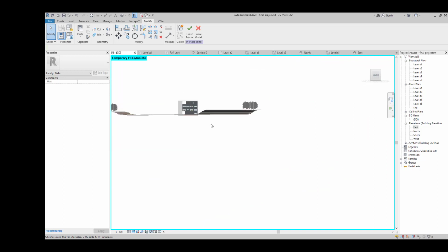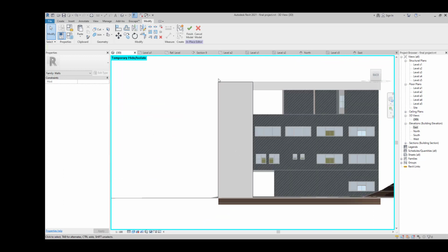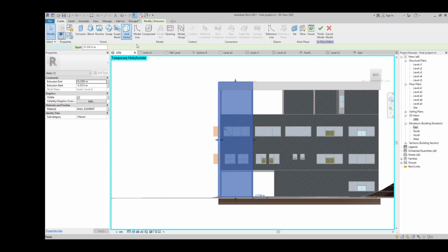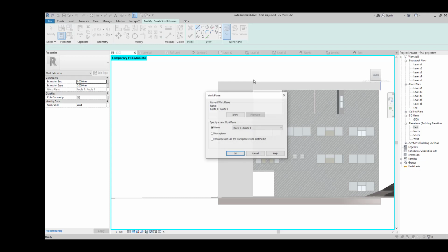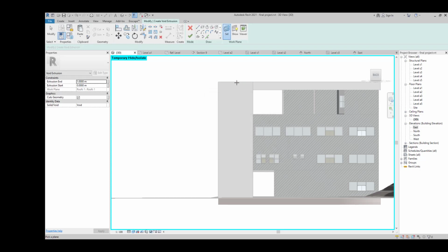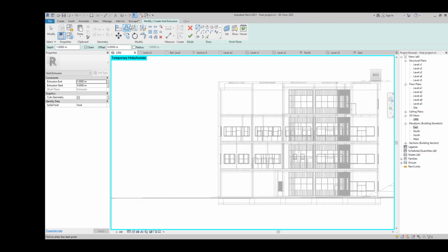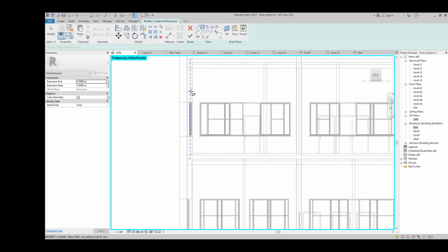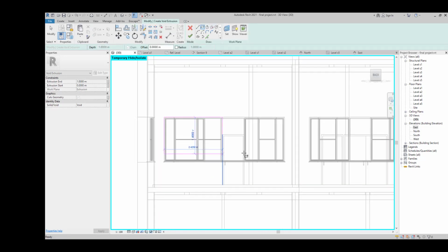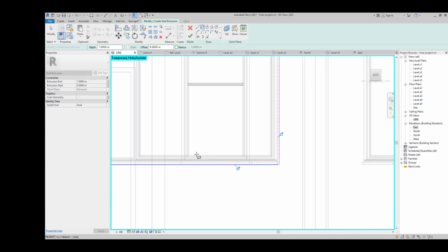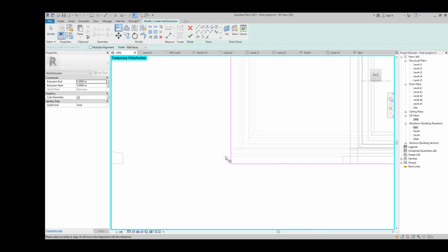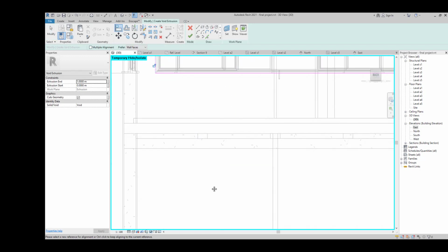I'm going to click back and choose my element. I'm going to create void and set a plane. It's much safer to set my plane. And after that, turning on the wireframe, start drafting my void here. And after that I'm coming here, then press align because we need to align our subject here as well.